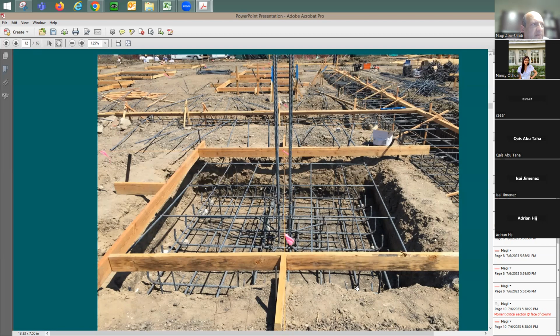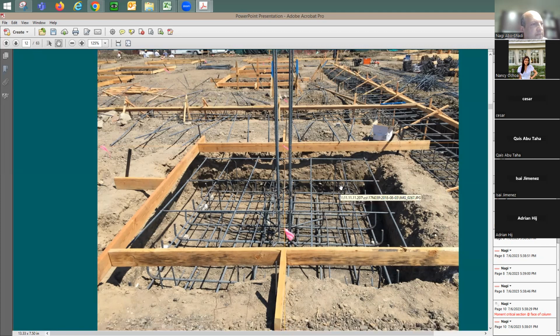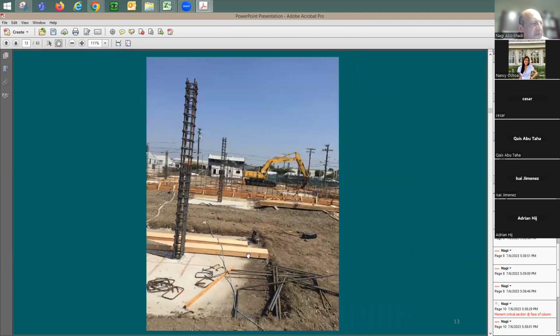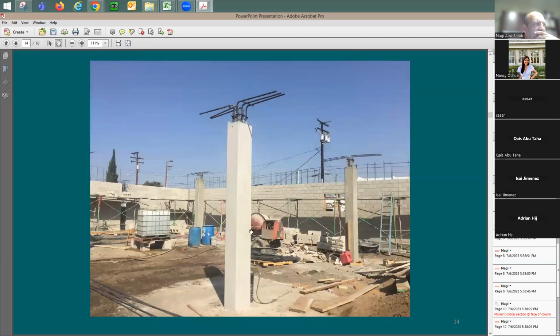And you see from this side, another board is coming by. But you need to understand that this footing was dug maybe 11 feet by 11 feet, or maybe 10.5 by 10.5, 10 feet and 6 inches. Here's the footing after we cast it, and you see here, they put the dirt back, and here's the column. Later on, they put some formwork for the column and continue building the entire building. Here are the building columns, cast already. So here without, and here with the concrete cast.